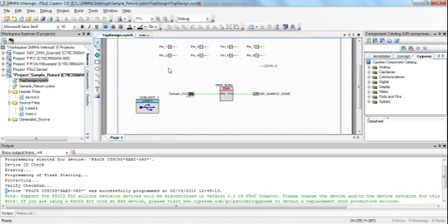There's a couple main components. There's a USB UART component, a DMA buffer, an ISR, and a clock. The clock runs and sends requests to the DMA buffer to go out and move data from the port 12 pin state register to another array specified inside the code.